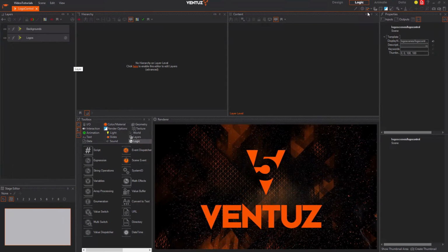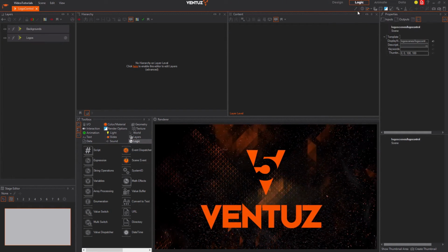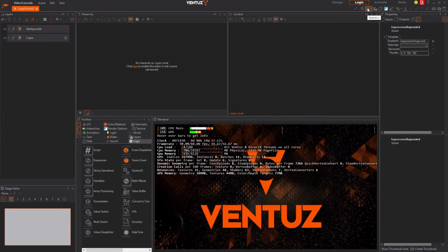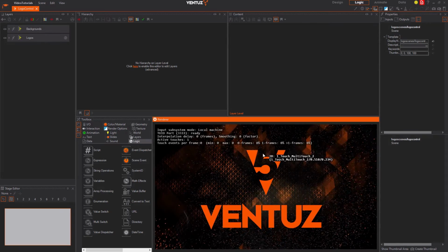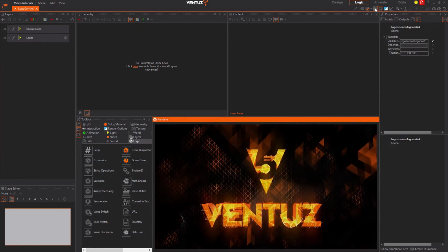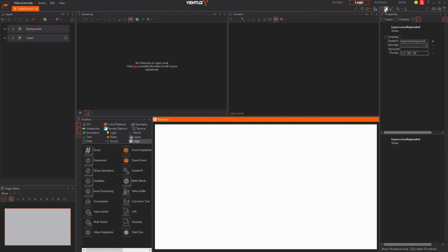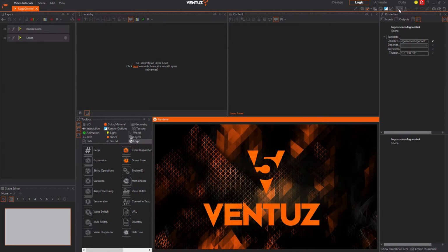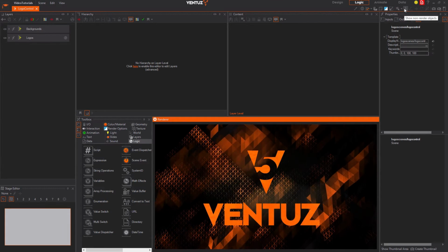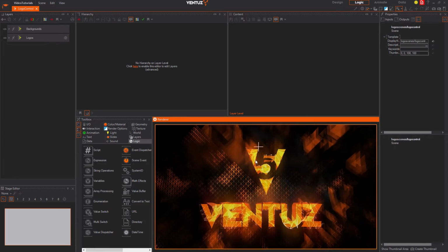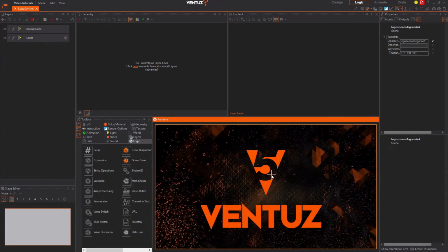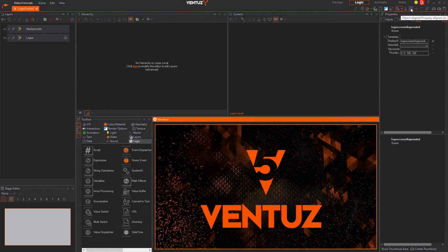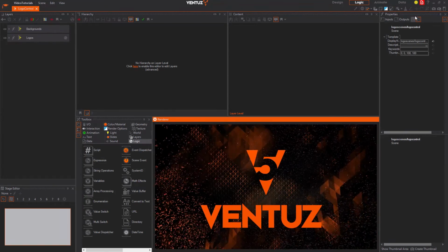Just below the View buttons, you can see options for the renderer. You can pick a color and copy it to the clipboard. You can switch wireframe view on and off, show the performance statistics of the Ventuz runtime, show diagnostics of the touch input, show bounding boxes of the selection, show the output's alpha value per pixel, switch to full screen, turn renderer edit mode on and off, which will enable the transformation gizmo on selected objects and also the free flight camera. You can show or hide non-rendered objects like cameras or lights, and you can change the mode of the transformation gizmo.